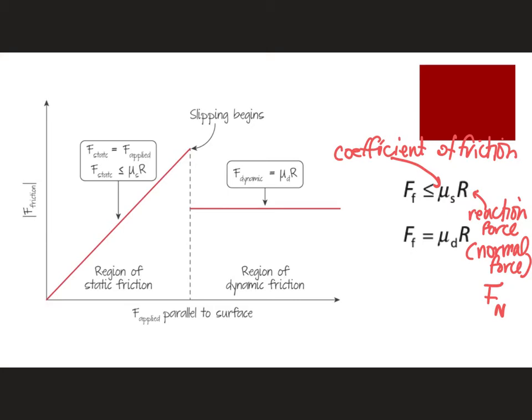And one last thing about this coefficient, we can see here that we've got the force of friction equaling this coefficient times another force. That means that this coefficient is just to do with the ratios and it has no units. This value should be small, less than 1. I can't remember if that's a rule, so be careful with quoting me on that. But I can't think of an example off the top of my head which would ever give a value greater than 1.